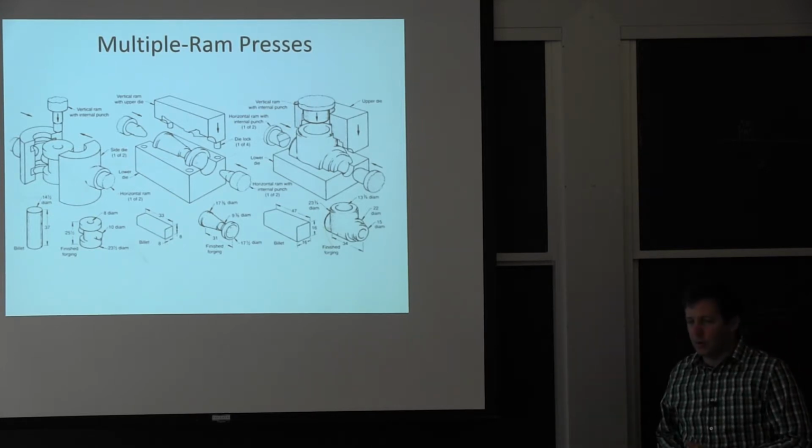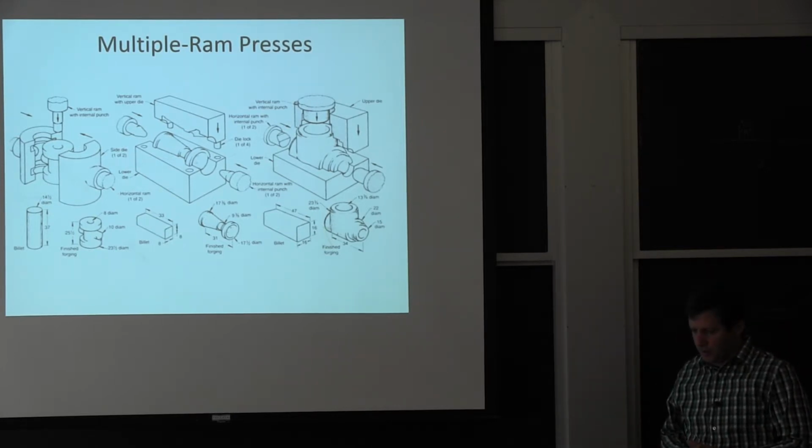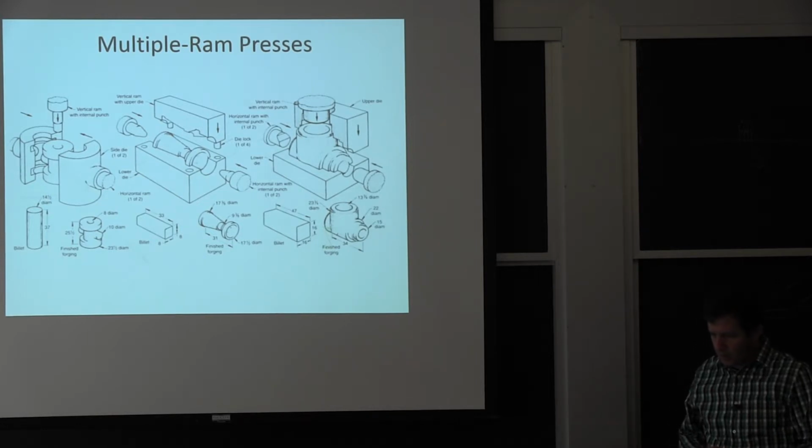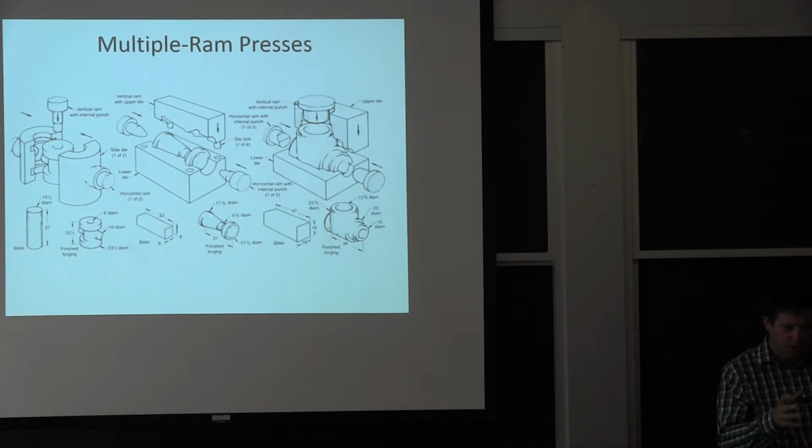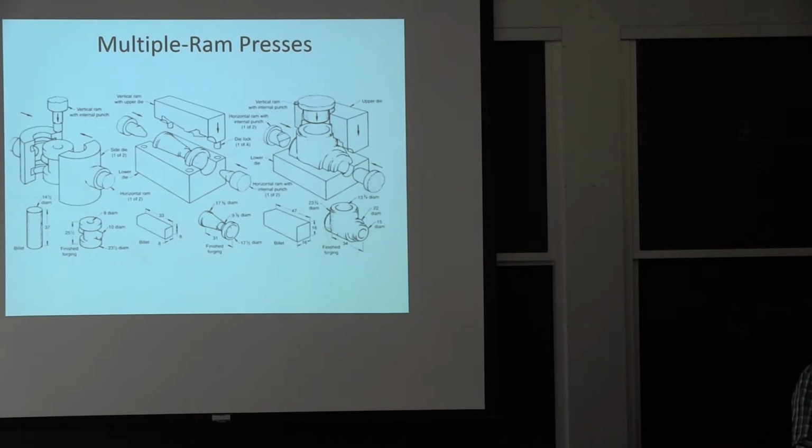So they forge components. We worked on a project where they were forging the base plate for electrical panels. That was Siemens, I think, or their competitor. And to make the tabs and all this, there's just a lot of operations. They wanted offset and all that, so they were using a 2 or 3 forge operation to make a complex shape out of aluminum.